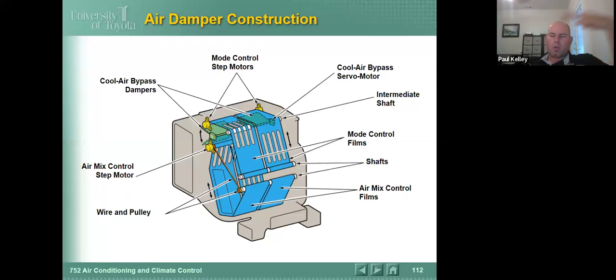If it's a broken door, the HVAC box is coming out. If it's a broken film, the HVAC box is coming out. So all we're really doing is making sure that the motor and the actuator work. Sometimes that takes disconnecting it and moving the door. And if the door is messed up, you can feel it.